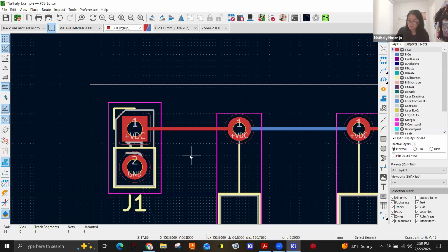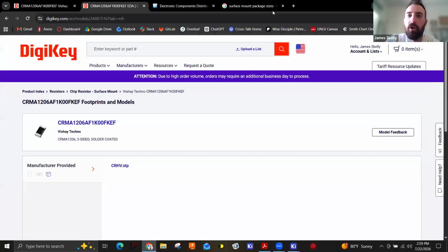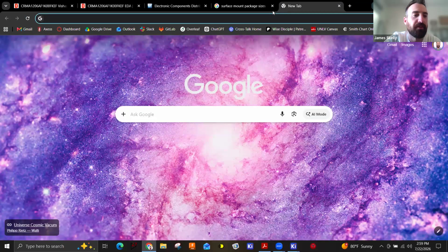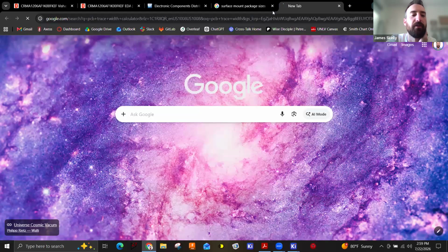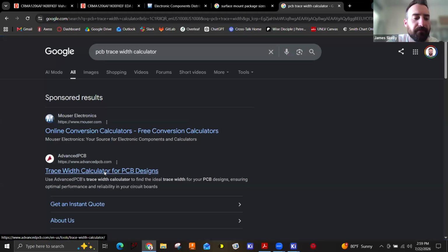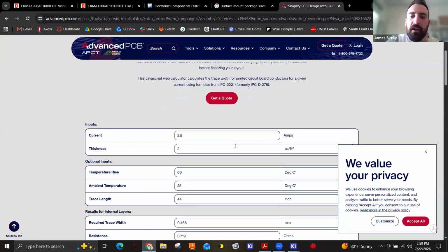So let me show you online. There are all kinds of PCB trace width calculators. If you just type PCB trace width calculator, you'll find these all over the place. There's all kinds of free ones. And if you're like, okay, I want my current to be 5 amps, that's a lot of current. Let's just say 1 amp.